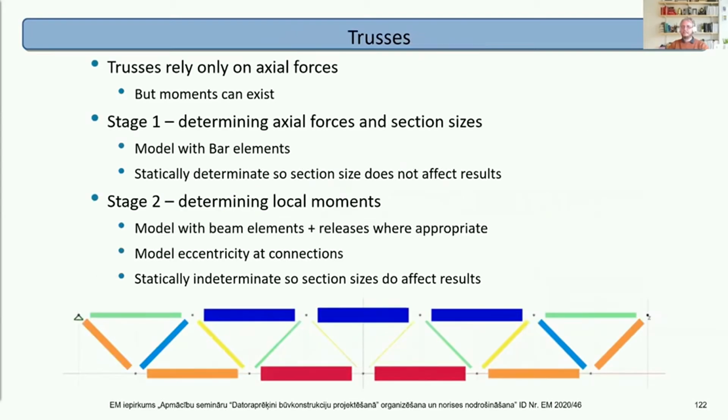Okay, for this type of truss, sometimes at the support there is some eccentricity. This inclined chord is not exactly in the support, but it's offset, and then this top chord is in a very short span, working like a beam. Let's say. Do you recommend to design it as a beam, or to do something differently in that area?